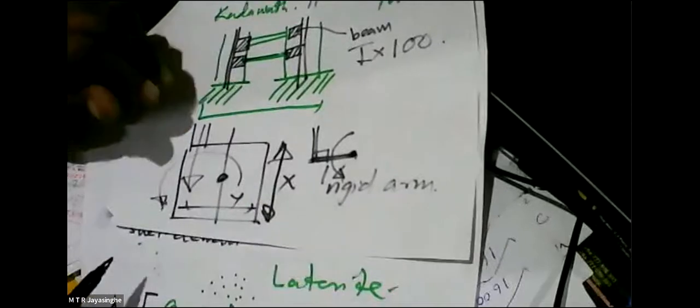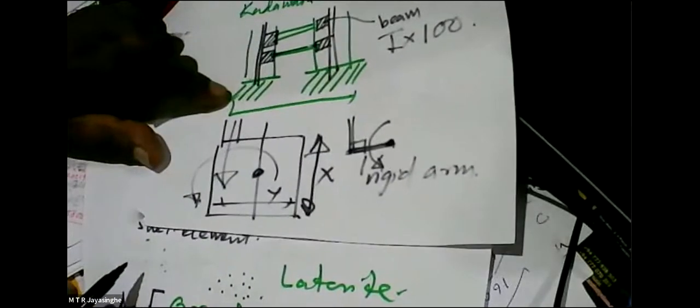And if you have rigid beams, transfer beams, this can very easily happen when the walls are on the beam, but not at the center. Walls will be selected by the architect, because the architect will have their own requirements of partitioning. So we can't always have the walls on the center of the beam. Sometimes they can be a little away. And because this is a transfer beam, we make sure the depth X and the width Y are more or less the same. Then you'll get the highest torsional moment resistance.